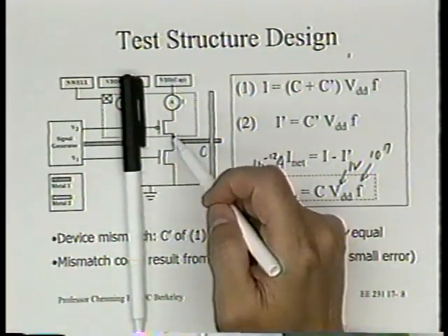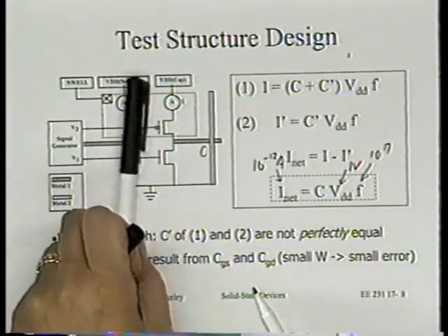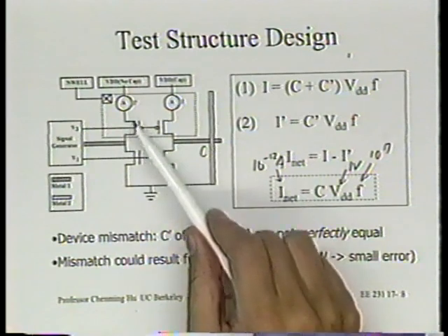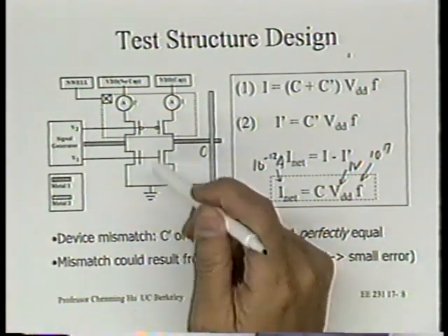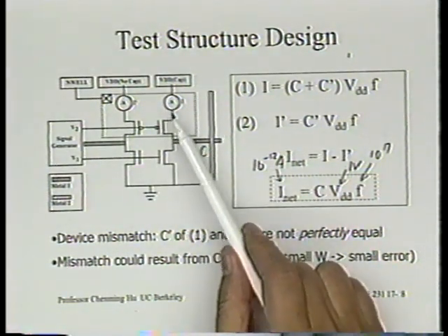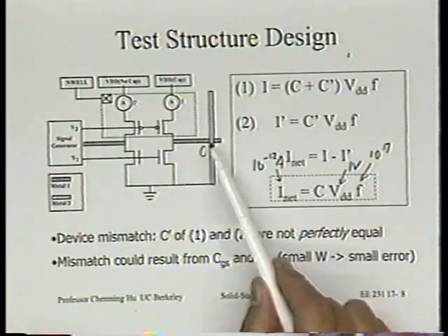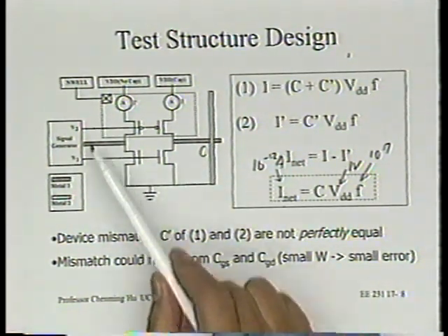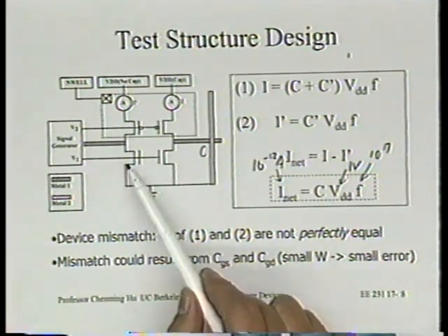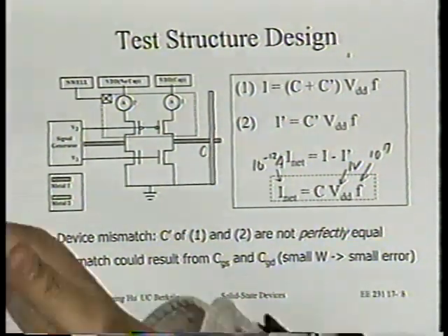we have some parasitic capacitance here, right? But we can deal with that by subtracting it out by putting a reference here. So we always lay this out with a reference next to it. Now, circuit designers will know that transistor matching happens to be very good. So we take advantage of that so that we have two structures. The only difference is that one has this unknown capacitance, the other does not. You notice that? This one does not have a cross point here. It still has the usual junction capacitance, right? And the other is straight capacitance. Do you follow what I'm saying?